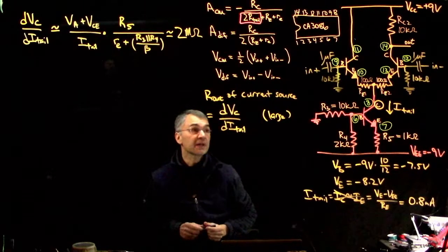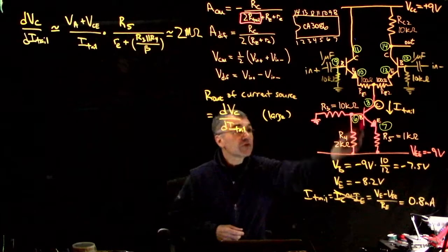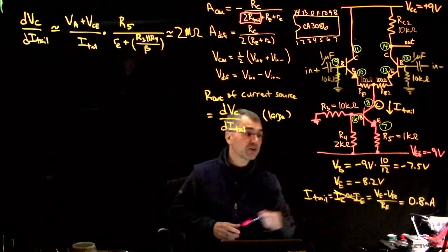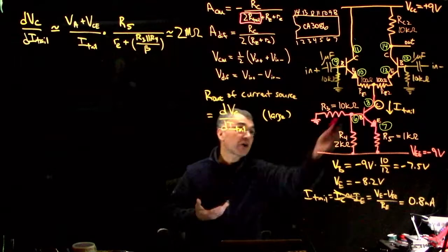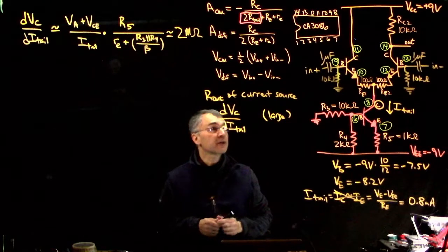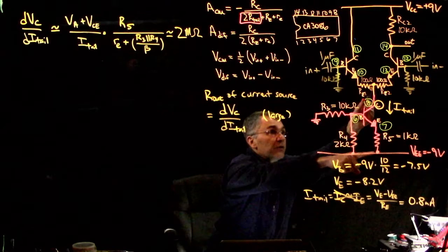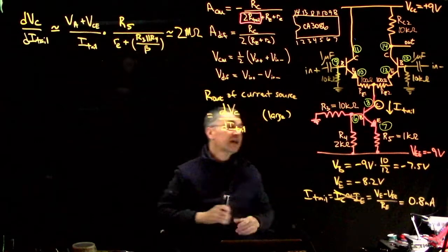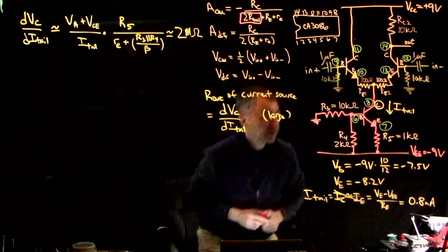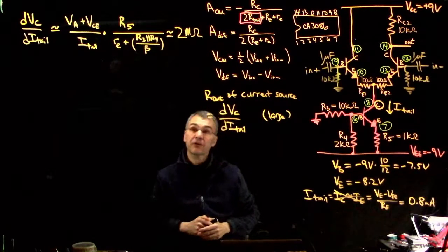And if you put a 2 mega ohm resistor here, remember that the whole purpose of the tail resistor was to flow a constant, little less than a milliamp. Well, actually, with the R tail, it really was pretty close to 0.8 of a milliamp. Because this was about a volt below zero, so we had about 8 volts, and we had about 10 kilo ohms, so it was roughly 0.8 of a milliamp flowing through the tail resistor, so then half went through this side and half went through this side. So we said, okay, let's try replacing that with a current source.